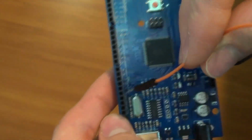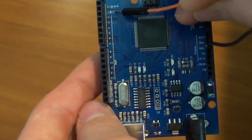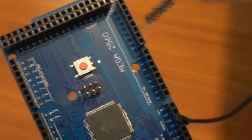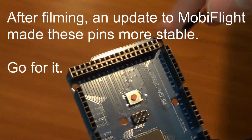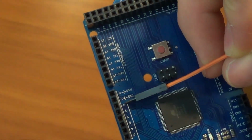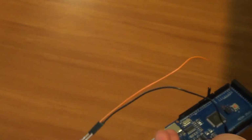And then this pin can go on to basically any of the pins with numbers here, except for 0 and 1. These are, I believe, communication pins and are not used by MobiFlight. You also notice you have all of these A pins, these analog pins, 0 to, I believe, 15. These are all usable in MobiFlight, but they're not 100% tested, so there might be a few errors in there, just to take note of. So I usually like to take pin 2, the first available MobiFlight pin. And you can just plop them in with these wires here.